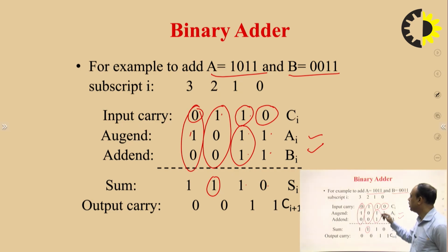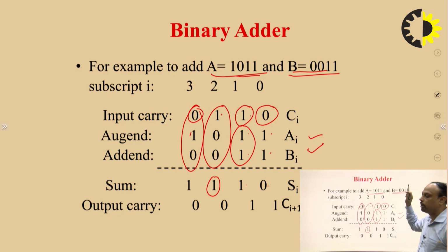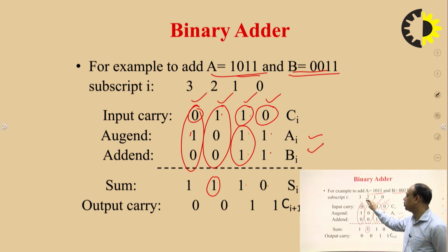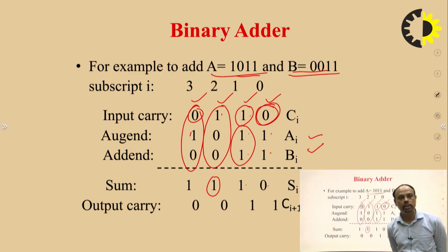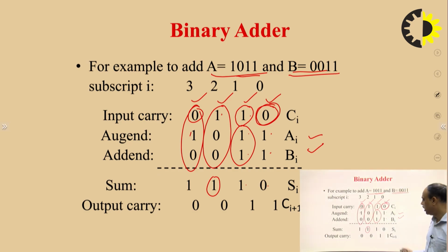If we want to add a 4-bit number, we need 4 different full adders. One is over here, another is over here, third is over here, fourth is over here. In the first full adder, we have to put Cin equal to 0, as there is no initial carry, it is always 0. So we have the output sum and carry output, as we can see over here.